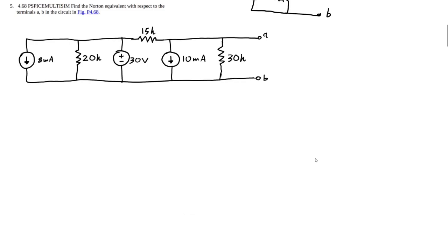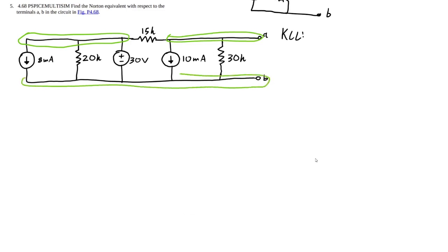Okay, so once again, we're going to go ahead and find a Norton equivalent circuit for this. And we're going to start with our universal method once again. So KCL, actually, let me label the nodes. So there's a node, and there's a node. Okay. So I'm going to call these currents, say this is I1. Let me redraw the arrow because it's kind of ambiguous. I1. I call this I2 and call this I3.